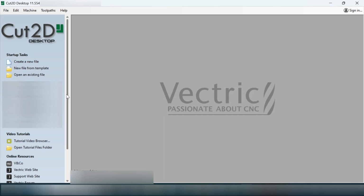He actually takes his image into Inkscape and creates it into an SVG after he does a trace on it. I found that I didn't have to do that because in Cut2D and other Vectric software, there is a trace function in it. So having said that, I'm just going to go ahead and create my new file.